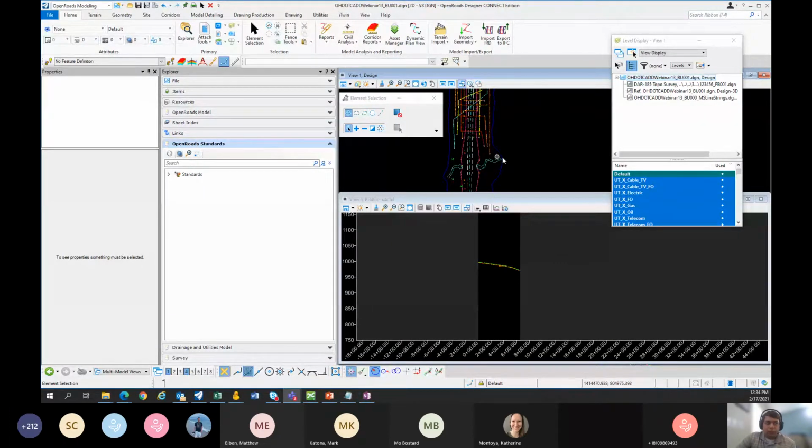So you could, I guess, trim your line strings back to where you want it to stop, if you wanted to do something like that before you extract it, those initial line strings. But I'm not aware of a way to restrict that extraction from the filter groups, because it's just looking at your criteria you set in your filter.